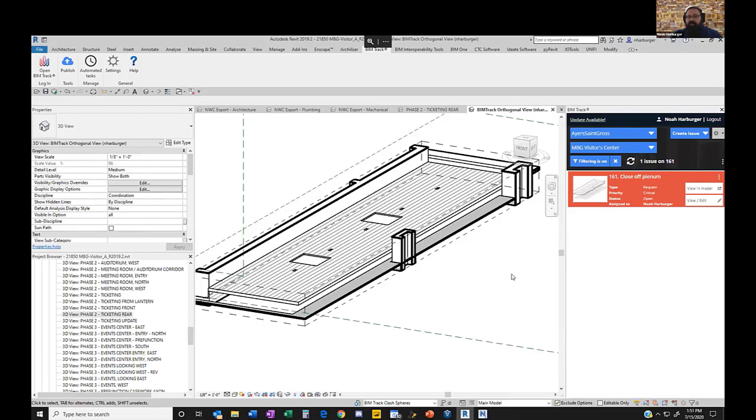Yeah, we have eliminated that. We don't push out separate NWC models. We create the NWC models up front just to keep things lighter in Navisworks. Technically, we don't even have to do that, because everything's through selection sets and not based on the models, we could just export one giant Revit model with all the links. I still do it because it's a lot easier when clicking on things to have that sort of aggregation of the different trades in the Navisworks space.